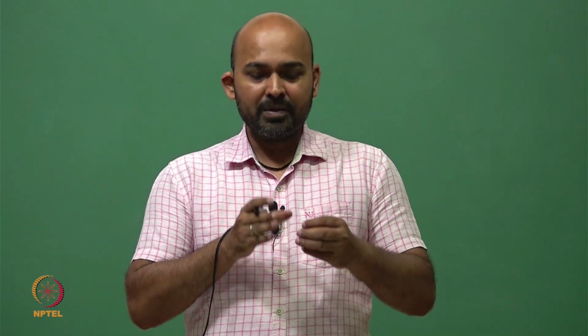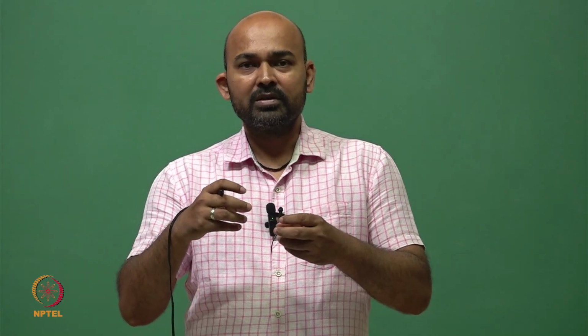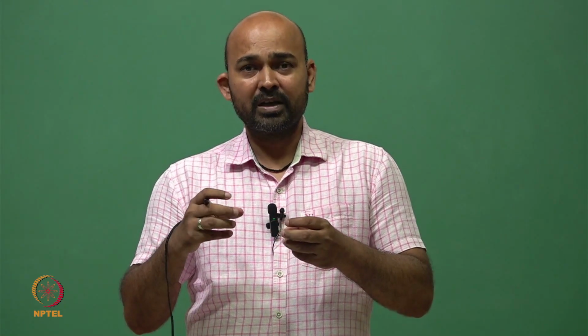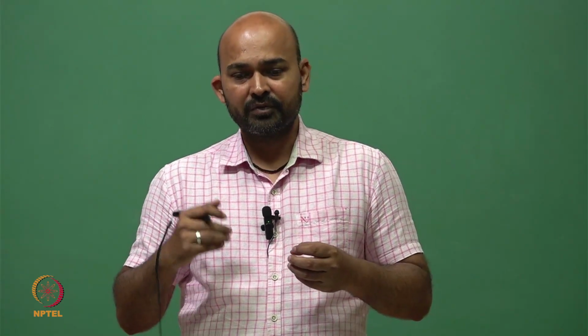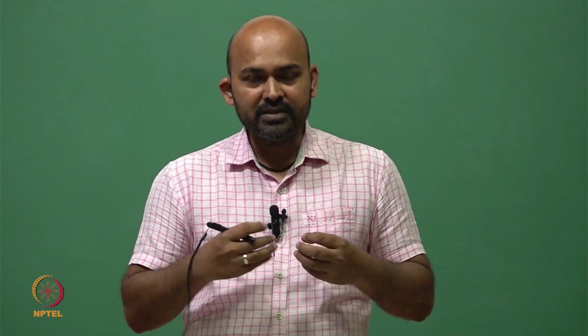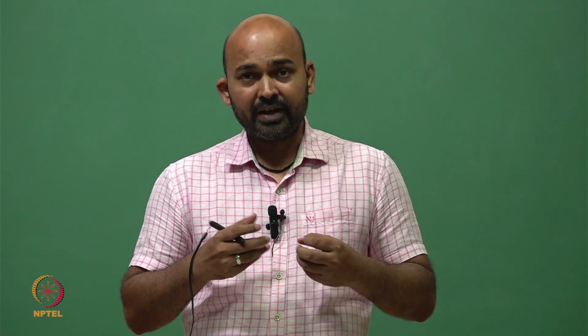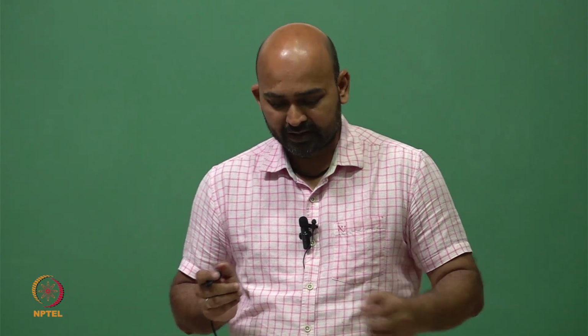However, in the extrinsic type, we are cutting this optical fiber. So now we can put optical multiplexers after this fiber, and we can connect multiple receivers at this point. So this is easy to multiplex in the case of the extrinsic type. The intrinsic type is difficult to multiplex.